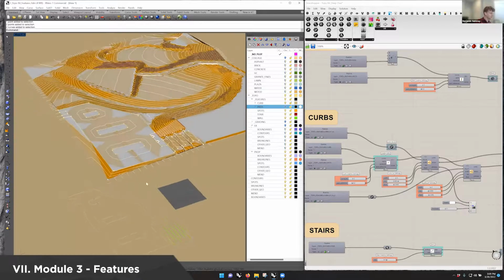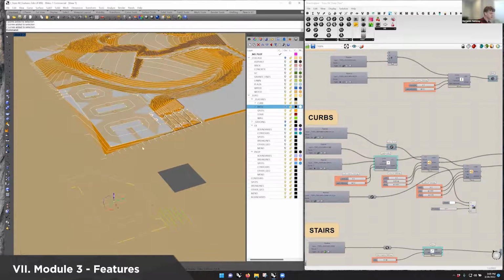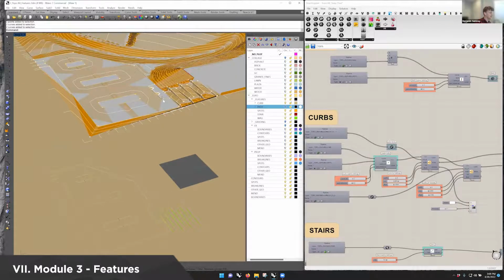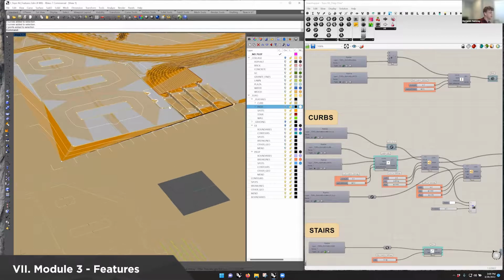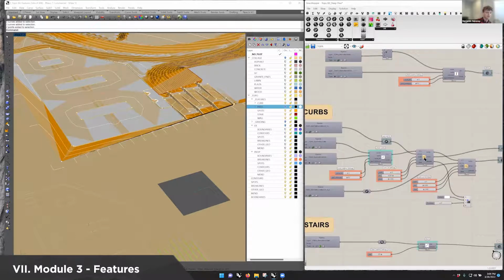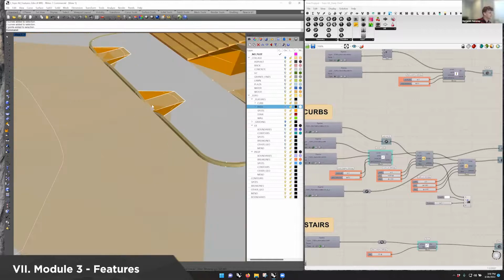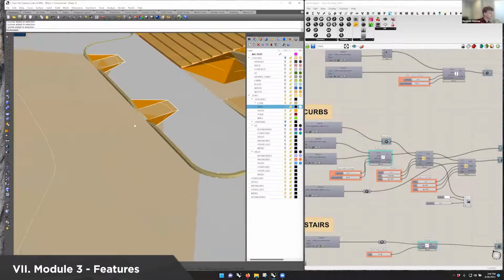You have the 2D curves down here that relate to the curves up top. And you have these spot elevations elevated in three-dimensional space in order to indicate where the top back of the wall curve is and the bottom front of the curve. The fun thing that we're doing here is that we're also adding in the modifier for curb cuts. And if I zoom in here, you can see a nice curb cut being created, but it's not using any spots at all.